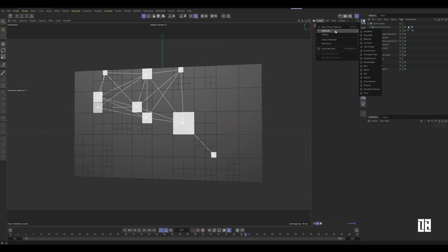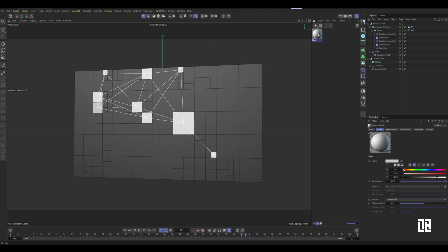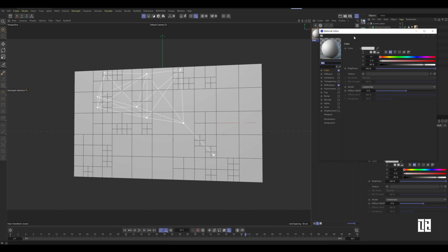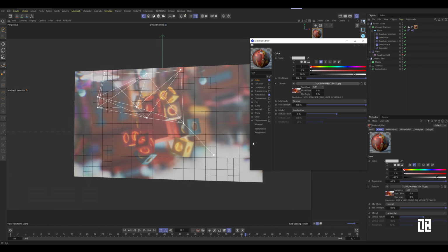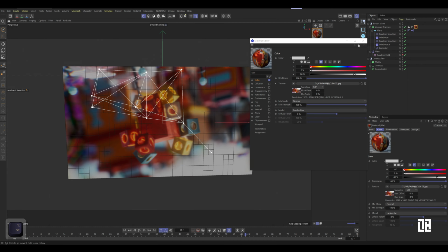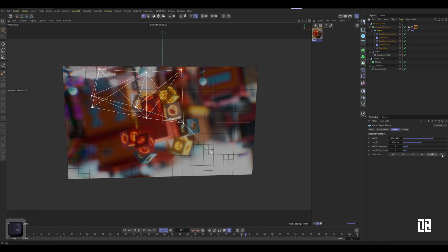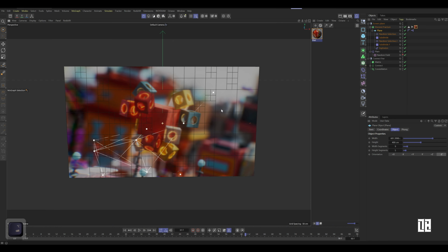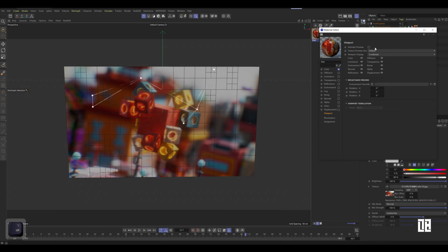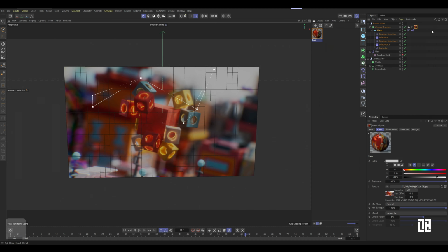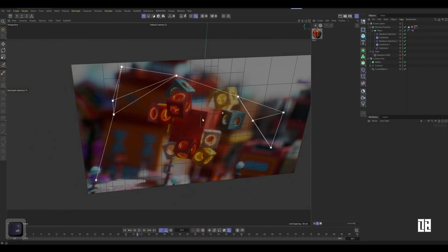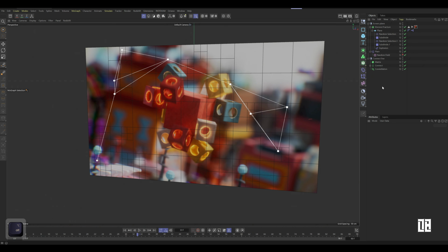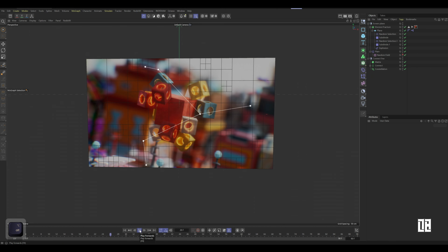Finally, set the material and render parameter settings. First, create a default material ball and assign it to the Voronoi fracture object. Load an image and cancel the reflection channel to observe the basic shading effect. The vertical direction of the picture is reversed, so the plane parameter is adjusted to -z. Now the axis of the line offset is reversed, and the position parameters of the matrix need to be adjusted.